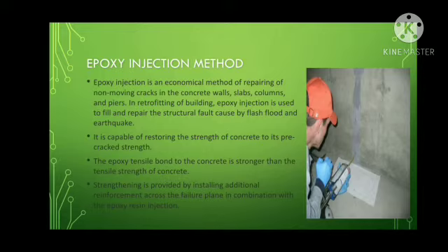It is capable of restoring the strength of concrete to its pre-crack strength. The epoxy tensile bond to concrete is stronger than the tensile strength of concrete. Strengthening is provided by installing additional reinforcement across the failure plane, as you can see in our image, in combination with the epoxy resin injection.